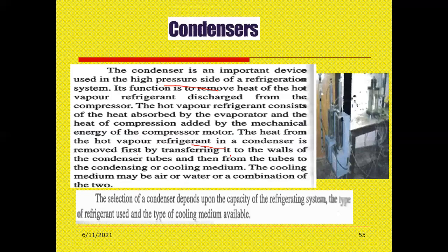Next, if you see the figure, that is a simple type of condenser, which is used for cooling the medium. The selection of a proper condenser depends on the capacity of the refrigeration system, the type of refrigerant used, and the type of cooling medium available.